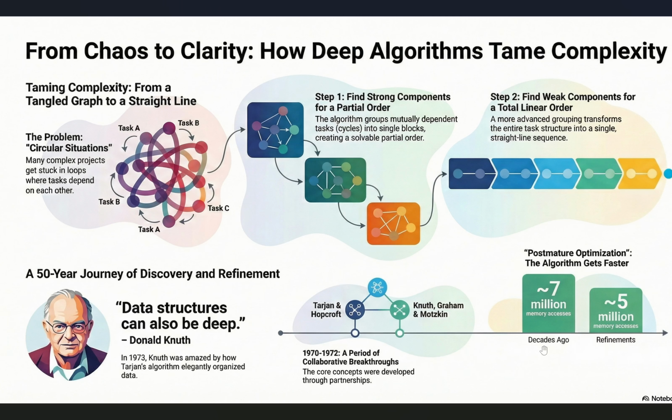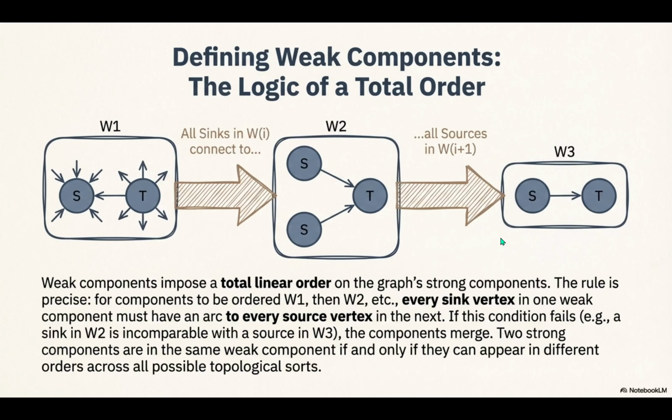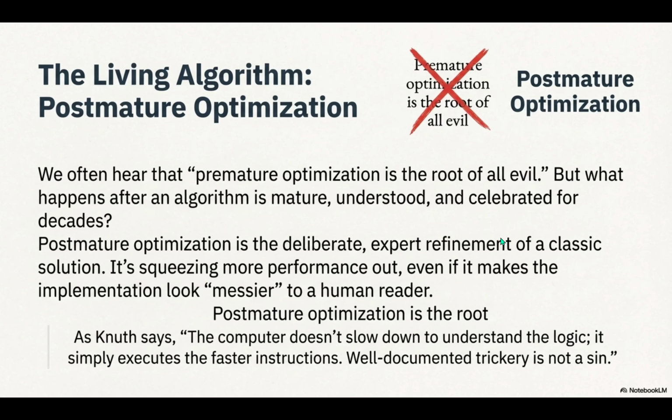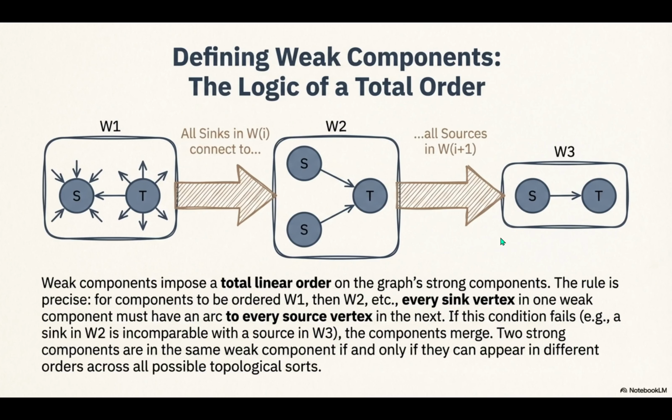And if even one of those 15 connections is missing, the strict sequencing fails because you can't guarantee a clean handoff. Some part of the drywall work might inadvertently start before every single part of the rough-in is truly complete. That makes perfect sense. If that condition fails, the blocks have to merge. They have to merge. And this logic is just invaluable for schedulers. It tells them exactly which tasks must be bundled together and managed as one big unit versus which can be neatly sequenced end to end.